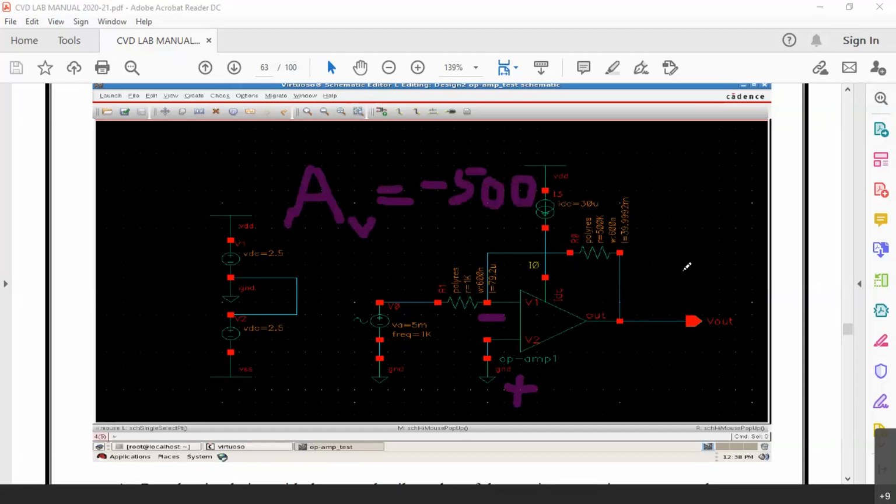The resistor will be of a much larger area when compared to the transistor itself. If you have to have a 500 kilo ohms resistor, a large area has to be reserved for it, as R is equal to rho into L by A. That is why this polyres is chosen. Otherwise, in the analog lib library, you already have a resistor, but it will not be converted into layout when you go for physical design, because the analogLib components do not have a layout part.